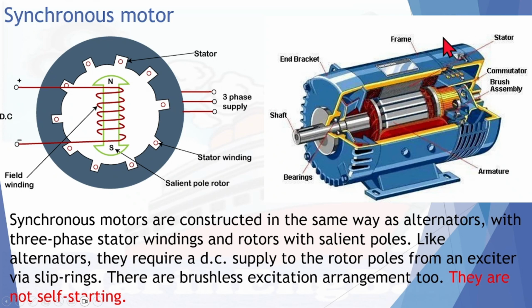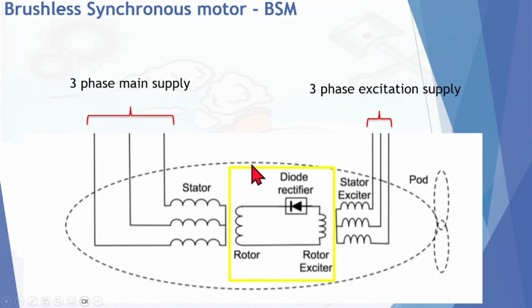So this is the construction, right? What we know, the synchronous motor's construction is the same as alternators, right? And it has no slip, no EMF induction, no torque produced, so they are not self-starting. So let's see how these motors are started.